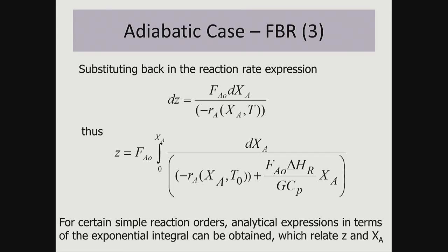You want conversion against length. Why? Because you want to look at the publications you've got, and you want to say, at this temperature, I got this conversion. Now I've got my reactor. I want to know, you can't just say, oh, all in. It starts at 0 and I got 50% at the end. You want to go 0, 1, 2, 3, 4, and build up based on your model for your kinetics. And remember what the kinetics are. The kinetics are first order, second order, but usually not that simple, so it will be additive orders. So think about Langmuir-Hinshelwood and think about power law.